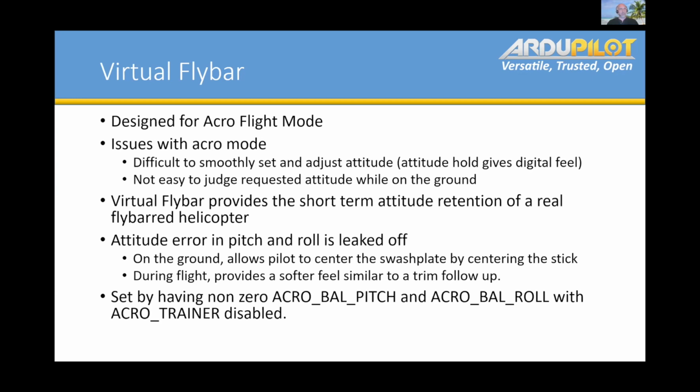I know Leonard, when I first talked to him about this, he was like, what do you mean you're going to leak off attitude? He's like, it should be following attitude exactly. So this really shouldn't work if you really tuned your helicopter well. What I've discovered now, and I'll show it later, is that there's such a delay in helicopters achieving that attitude that this comes naturally, that you're always going to be delayed so that you can leak off attitude. And so it provides a softer feel to the aircraft, also provides a little more safety on deck, and makes the aircraft a little easier to handle on the ground.